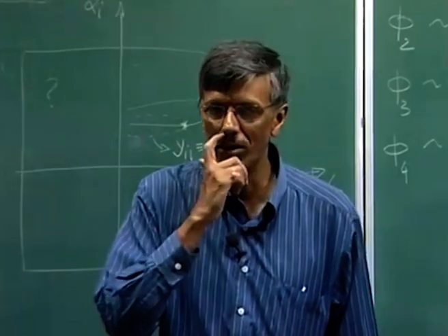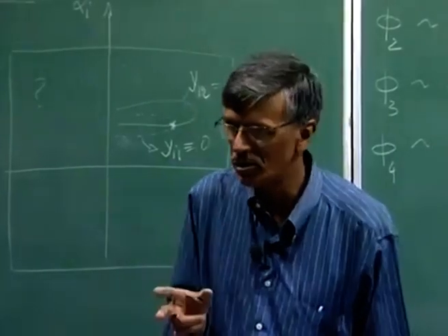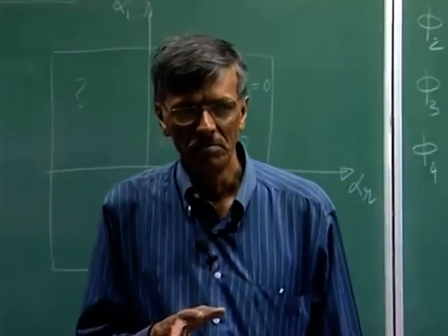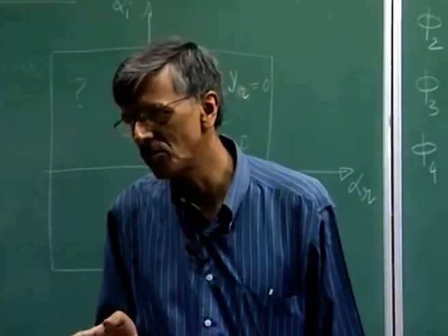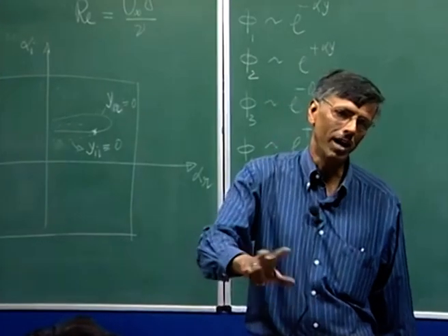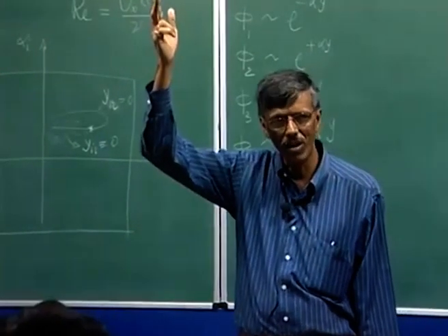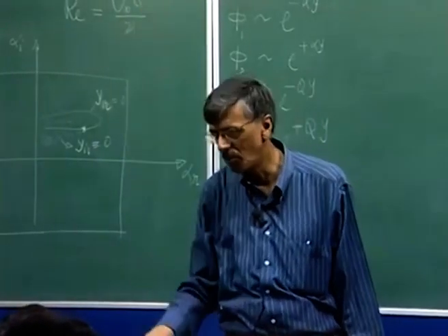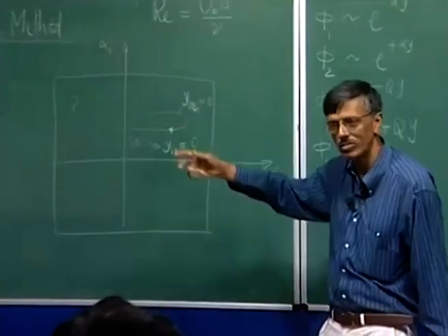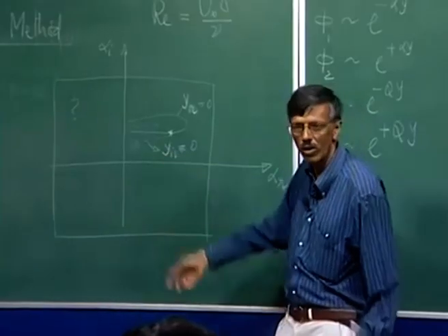So, it is very easy now for you to really do this grid search method. All you need to do is two sets of initial conditions. If alpha r is positive, you do what we saw in the transparency, and if alpha r is negative, we will have to make appropriate modification. And then we again go through that same exercise, come from the free stream to the wall and go ahead and do this exercise. So, I can automate this whole process and find all the values of alpha, and this